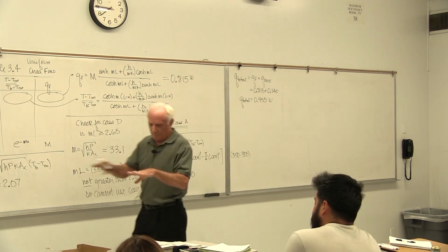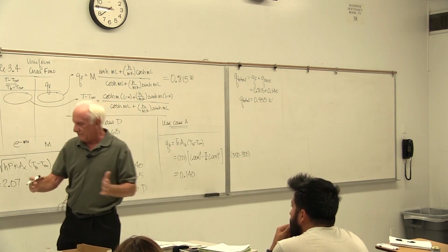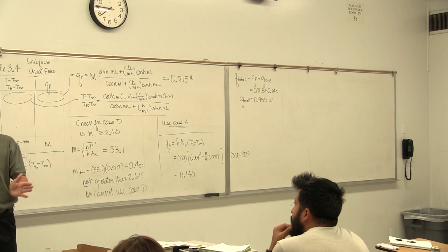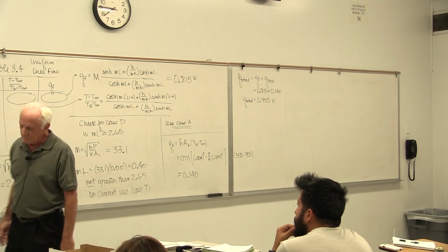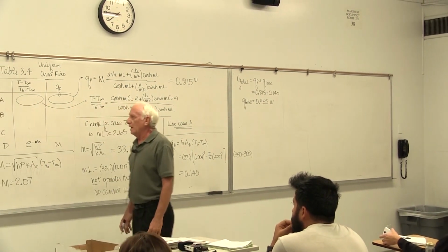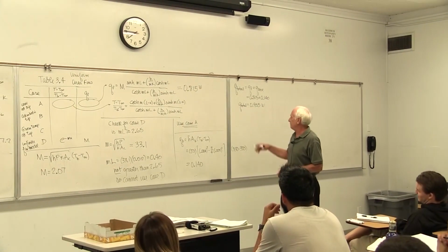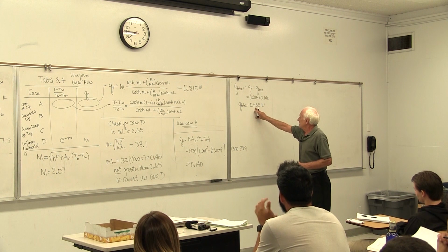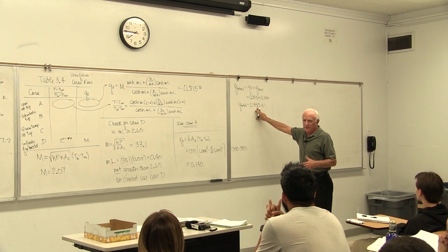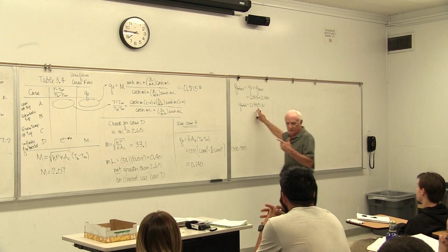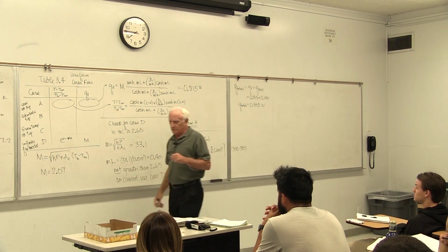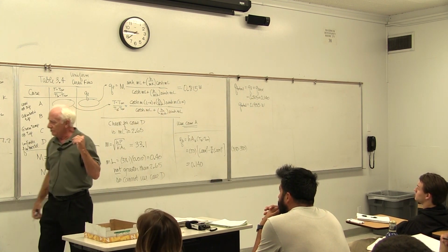I attach them to a base, maybe 40 centimeters by 40 centimeters. To dissipate 100 watts, just a real quick calculation, I think I probably need times 195, about 110, 120 of these pin fins on that sheet of metal. So I need that many pin fins on there to do the job, I think.